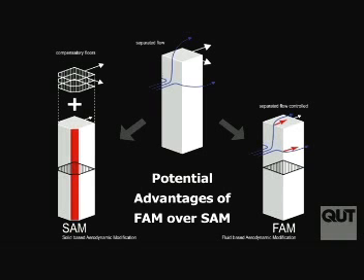And so the opportunity to make up for that and still achieve the same volume of rentable space typically means I have to increase the height of the structure. And that's a classic way of chasing your tail. You're now going to a taller building that's going to be more slender effectively and have greater response. And so that becomes an impossible journey, a Don Quixote challenge. What we were looking at at RPI with a couple of students of mine was to look at how we could modify the flow by injecting flow around the building to improve the performance, particularly in crosswind.